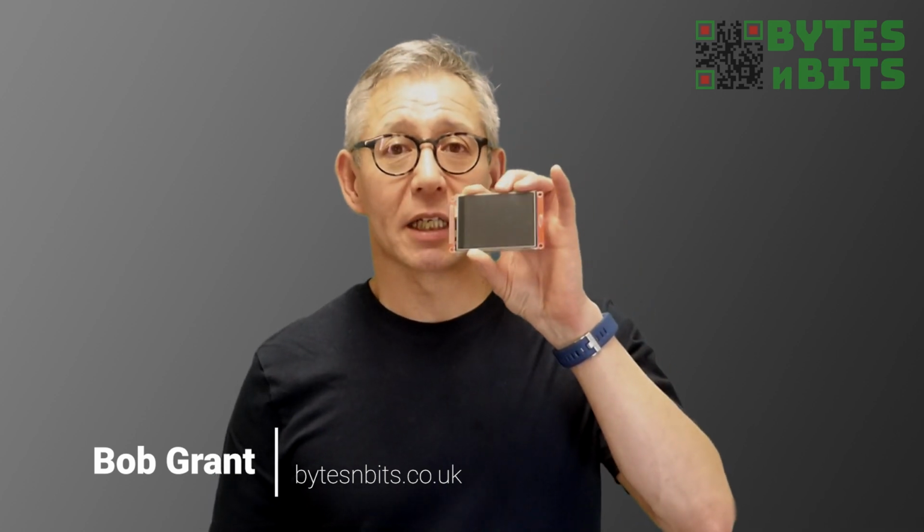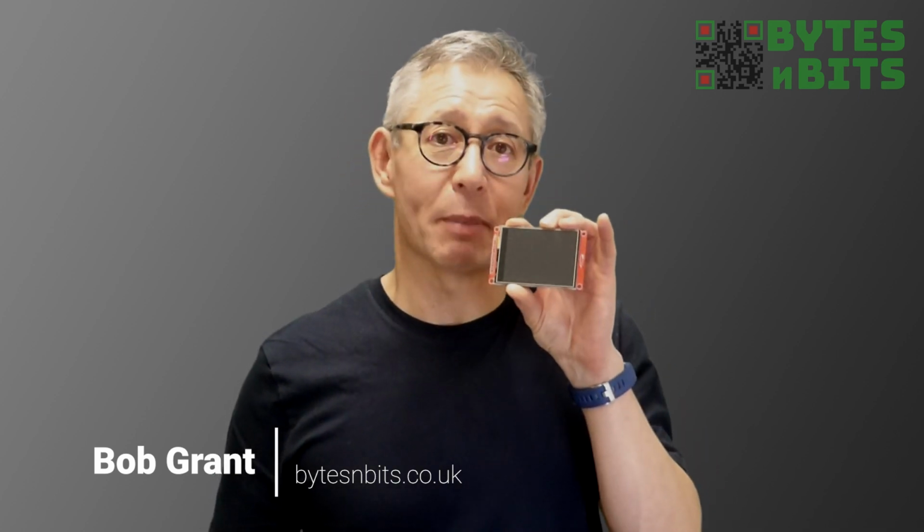You can pick up one of these little SPI-based LCD panels very cheaply on Amazon or eBay, and they're great for creating a user interface for your project or for creating a small gaming console. And connecting them to your MicroPython enabled Raspberry Pi Pico is actually quite a straightforward project. You only require 6 connections, and thanks to some great MicroPython libraries, driving the display is just as simple.